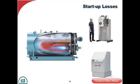The whole point is that if I'm starting this boiler to meet load versus this boiler, and they're both at ambient, obviously this boiler is going to heat up faster, and it's going to catch that load faster. No doubt about it. And so the engineer might say, all right, I'm going to put in a bank of these as opposed to 1 or 2 of these.